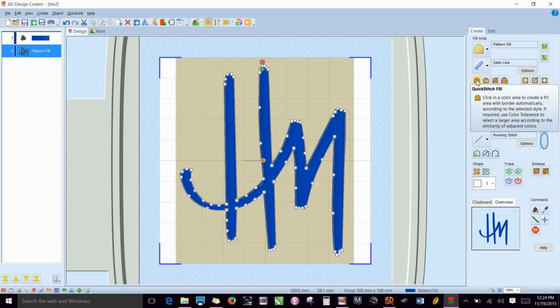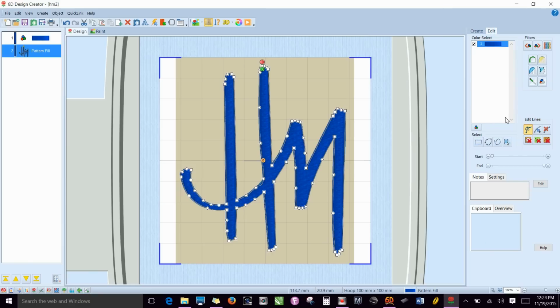But this is what we used, and it set the points automatically, and it also determined what it thought needed to be round nodes or square nodes. Now here's the difference. A round node is good for curves. It allows it to create curves. Square nodes, if you have a distance between two square nodes, it's going to try and make that as flat as possible. It will force stitching to be done at those exact points. Round nodes are a little bit more approximate and a little more curvy.